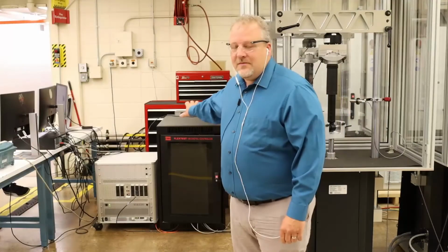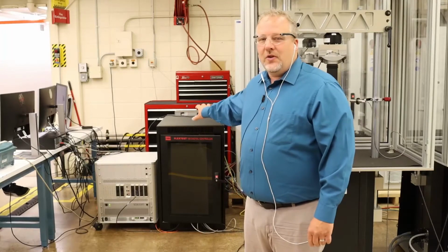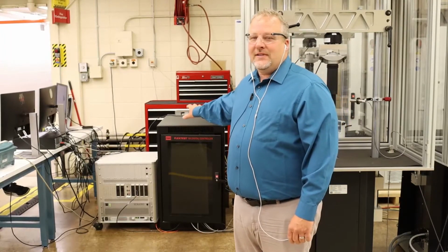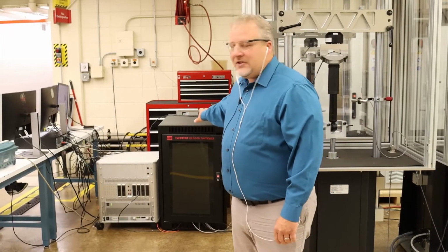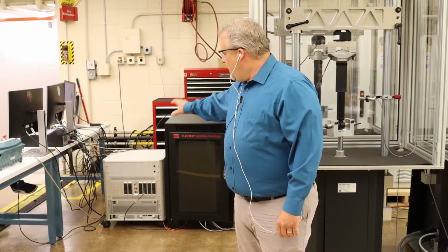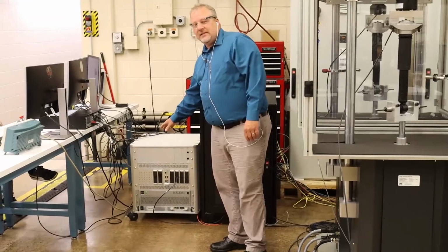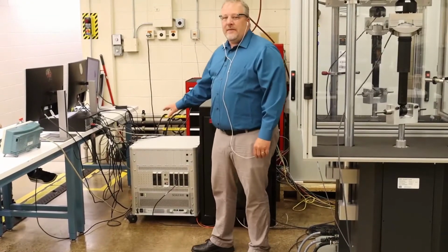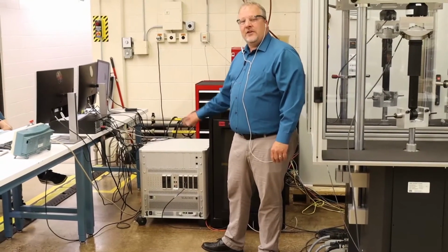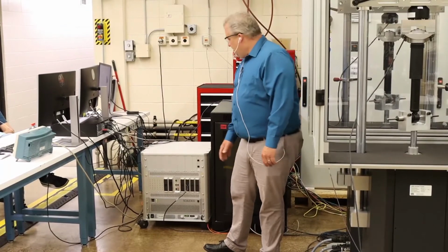On this side of the system, we have our FlexTest digital controller, which is used to control the loading rig inputs and outputs. It also has a communication interface and clock interface over to our real-time simulator system from dSPACE. This case is a dSPACE SCALEXIO system. This is where the real-time vehicle model software runs. In the demonstration today, you'll see CarSim running.